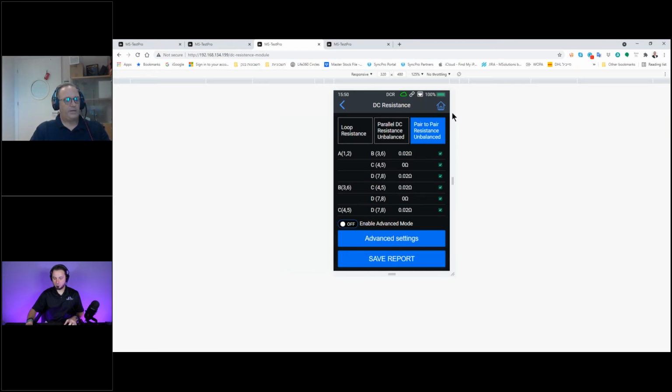It means that we have a wide range of mistakes that can happen. If we take, for example, a category cable with a 28 ohm DC resistance on the twisted pair, I can assure you that this cable will not work for 100 meters with HDBaseT. No matter what you are told, even at 70 meters, it will not work.